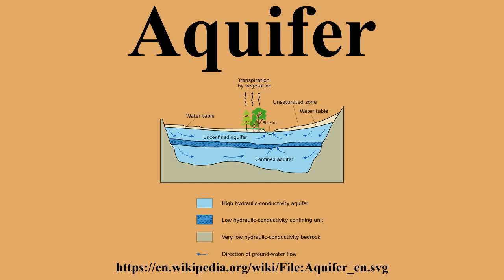Saltwater intrusion. Aquifers near the coast have a lens of freshwater near the surface and denser seawater under the freshwater. Seawater penetrates the aquifer, diffusing in from the ocean, and is denser than freshwater. For porous aquifers near the coast, the thickness of freshwater atop saltwater is about 40 feet for every 1 foot of freshwater head above sea level. This relationship is called the Ghyben-Herzberg equation.